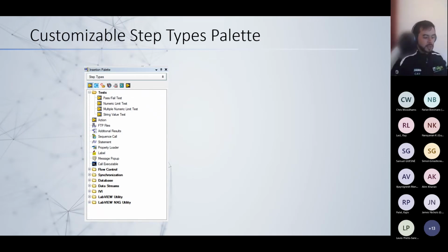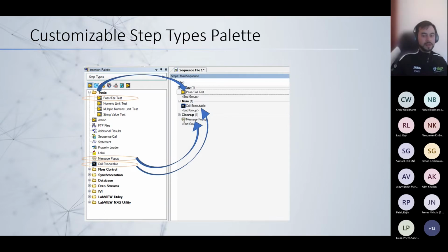The idea is TestStand is comprised of a palette of action steps. You can see on the top there different adapters, as they're called in TestStand, for different languages: CVI, LabVIEW, C, .NET, even LabWindows as well. But then you can use these adapters and incorporate our modules in different languages. And the good thing is, in TestStand, you have the concept of a sequence. In the sequence, you drag and drop your steps, and the sequence shows the flow of your tests. Everything becomes standardized: you log per step, you set a pass-fail condition per step, and stuff gets more standardized.